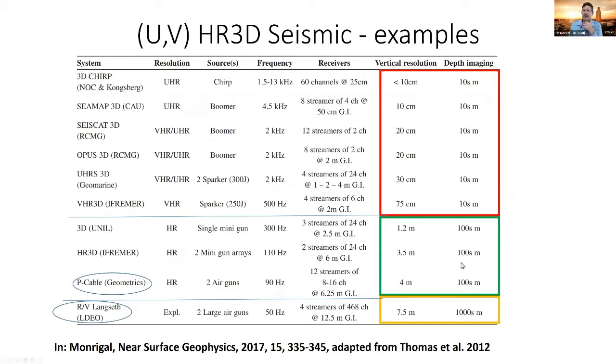Then there's another suite of technologies having a vertical resolution in the multi-meter range, investigating depths somewhere in the hundreds of meters subsea floor. That can depend a lot on the energy of the source and design. Then there are the things we're very familiar with, like the deepest one at the bottom, which would be nominally kilometers of investigation and maybe vertical resolution in the 5 to 10 meter range.